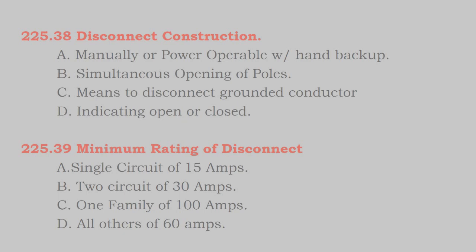And then we get to the all others of 60 amps. What we'll see later on is that for supply side connections, they're really looking for a 60 amp connection, as far as the minimum cable gauge and rating for that supply side connection. Not that you can't have a 60 amp rated main breaker and a 60 amp rated cable and then plug in a 20 amp microinverter. But most of those supply side connection taps on the market are for heavier gauge cable that is associated with 60 amp service.